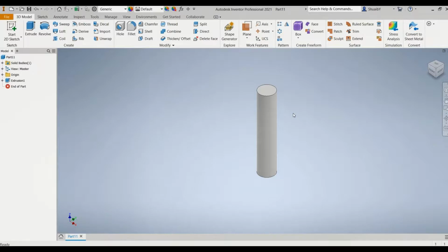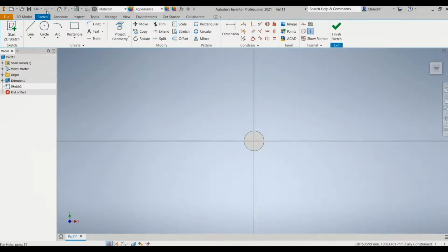Now the next step is to do the pier cap. So again, I've chosen something that's not too easy and also not too difficult, okay? Now what we're going to do is draw that. I've selected the rectangle and I'm going to make the distance 3 meters. Now, very important, as you're seeing me typing these dimensions, these have to be written exactly the way you see on your screen, because those are the parameters that will be read in Infraworks. So you see, I've done the right view. We also need to delete that center line because Infraworks is very, very sensitive to overlapping geometry.